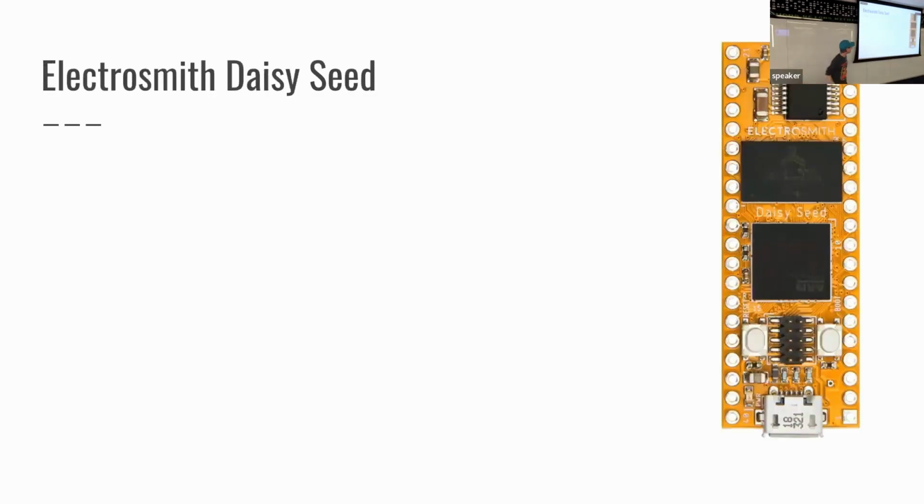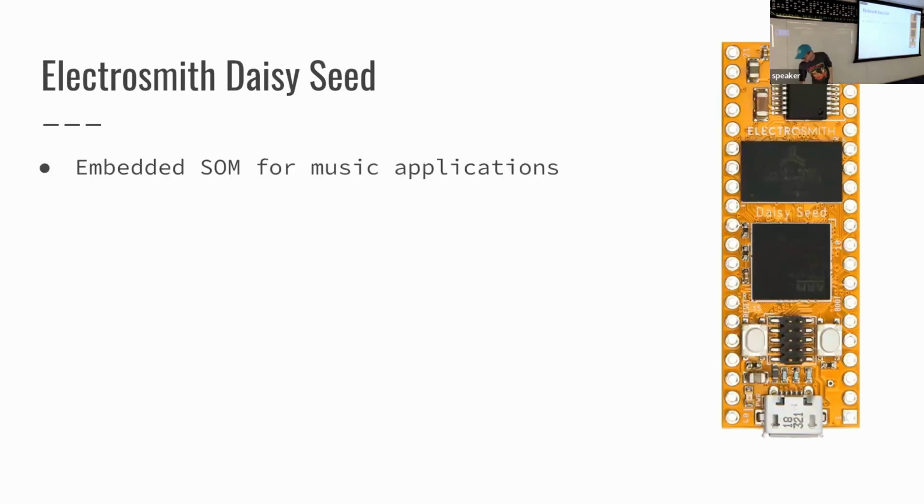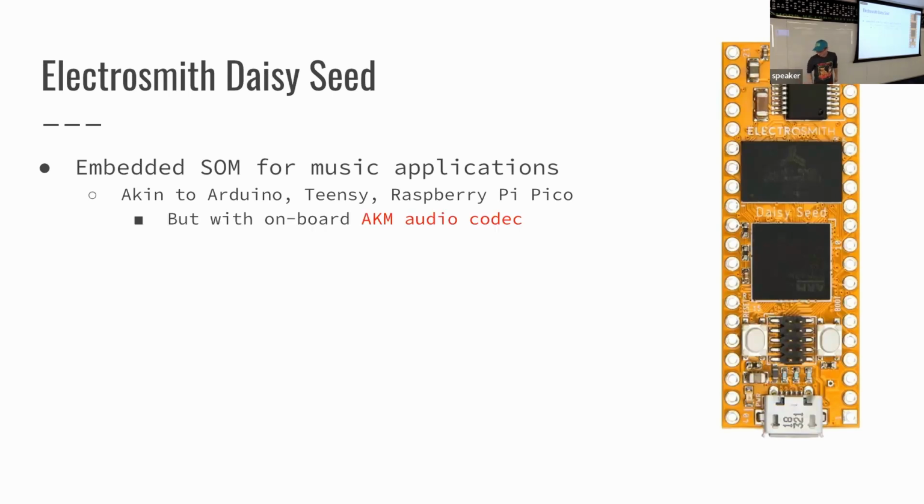And the synthesizer itself, this is the big version of it, down to scale. It's an embedded board. It's similar if you've heard of Arduino or Teensy or, more recently, the Raspberry Pi Pico came out. It's not similar necessarily to a regular Raspberry Pi, which you may have heard of, which would be running embedded Linux, probably. It's a bare metal platform. The thing that sets it apart from the others is that it has the audio hardware right on there. That's an audio codec. You'll notice the text is blurred out because the factory burned down, and they're working on resupplies.